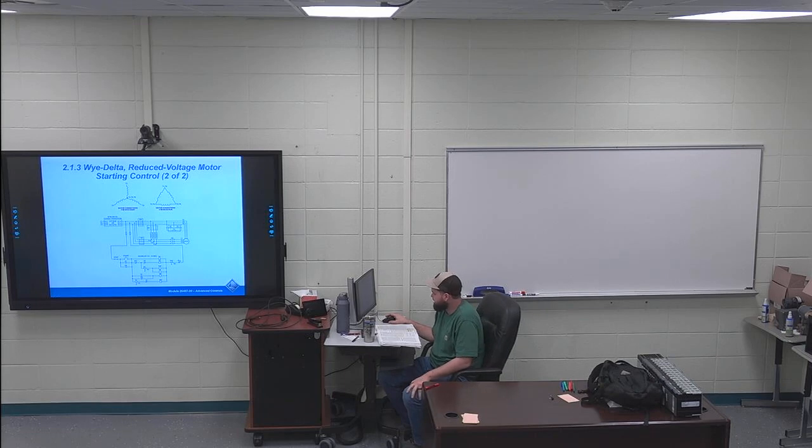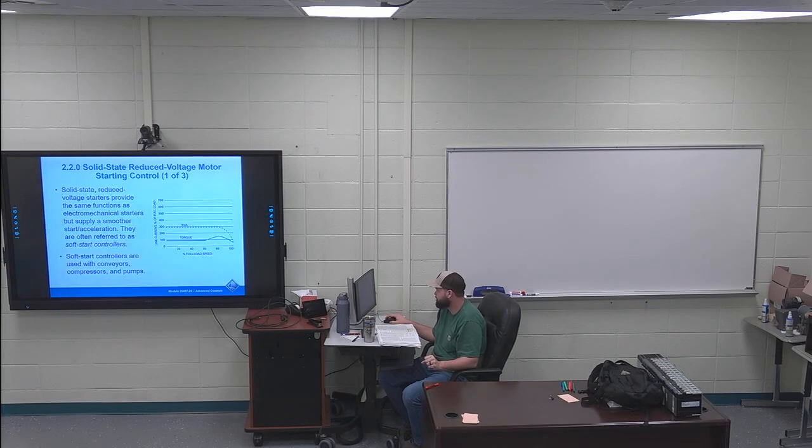Moving on to page 17, 220, solid state reduced voltage motor starting control. First two sentences of 220 are highlighted. Solid state reduced voltage starters perform the same function as electromechanical reduced voltage starters, but they provide a smoother stepless start and acceleration. For this reason, they are often referred to as soft start controllers. These are referred to as soft start controllers, what you want to key in on in 220. Soft start controllers is what it has up here on the board.